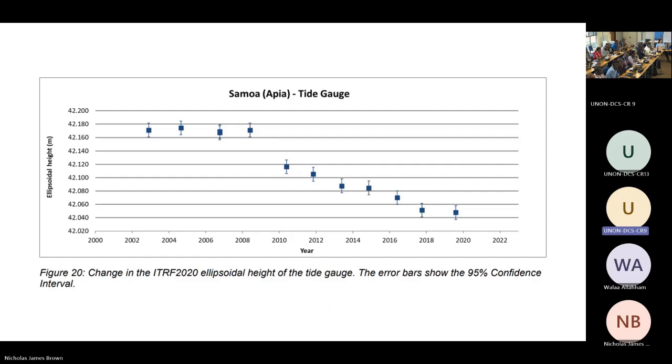Yeah, thank you. In South Africa, we have a bit of a challenge in trying to define the reference frame. We have a horizontal datum on land, Hartebeesthoek 94, aligned to ITRF. But we find it difficult to define the reference frame for coordinates in the ocean. People are asking us, even if you say it's Hartebeesthoek or ITRF, how do they realize it?